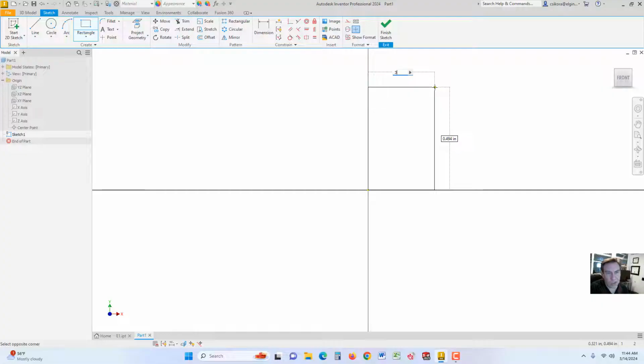Okay, now we want to get that other one over there. You don't want to move over and click on it as much as you could just hit the Tab key in the upper left corner of your keyboard, and it will automatically go to the next one. Now you could type in 5 inches in height. Again, you don't need to type 5.00 unless it's 5.125, of course, that's when you would use that. All right, and hit enter.